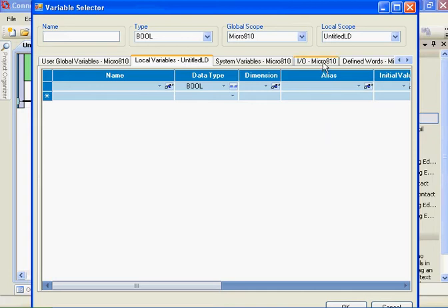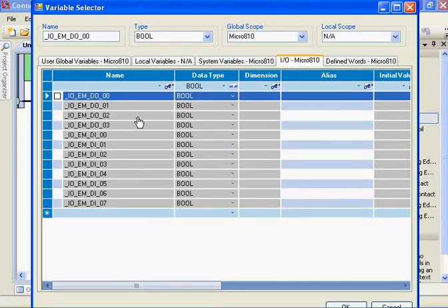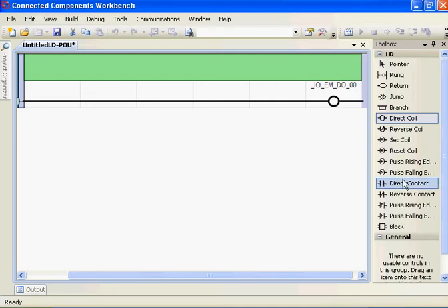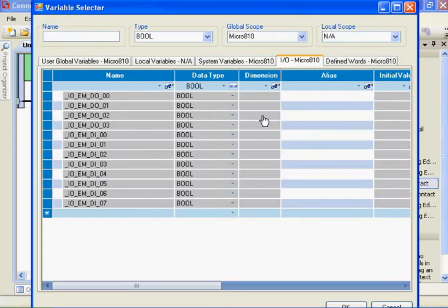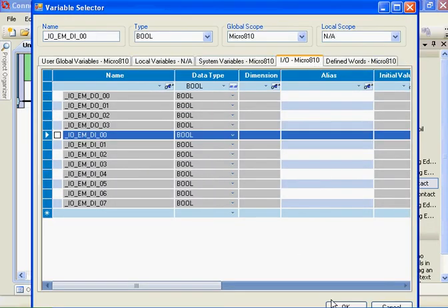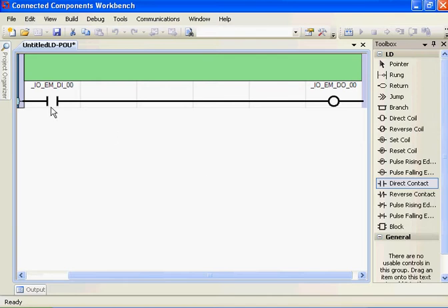Let's have the red LED being turned on and off when I hit two buttons together in logic AND fashion. I'll first make the output button 0, that's the red LED, and now start having two buttons. If I want this light to turn on when button 0 and button 1 is turned on, have two contact switches in series. I'll have input number 0. So now if I push button 0, the output turns on.